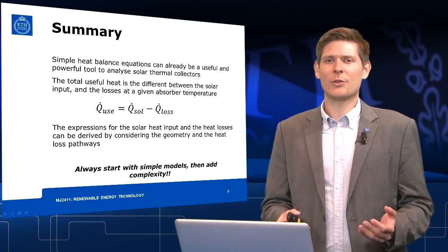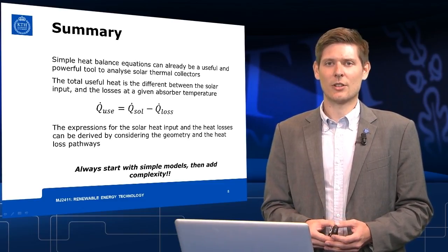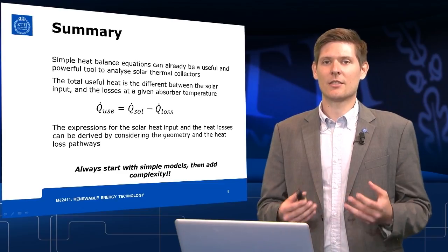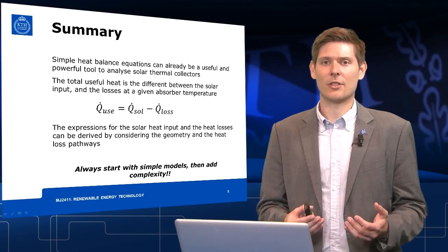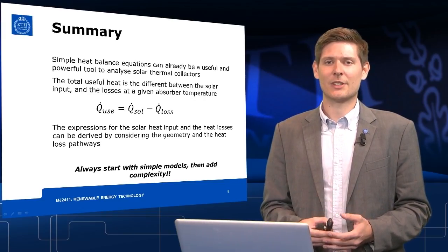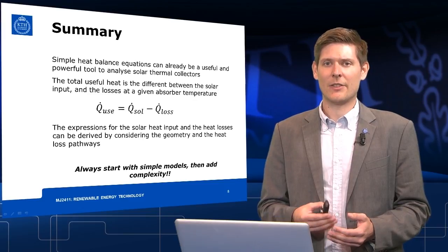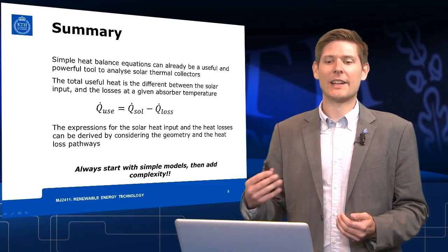What I want to stress very much is that in order to calculate a solar collector, you need to be aware where to draw your boundaries, where you're going to have your control volumes, and you always want to start with a very simple system. And once you have established a very simple system, you're going to add complexity.